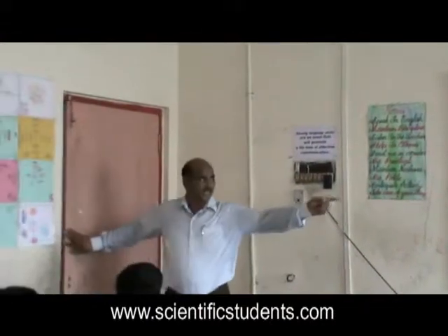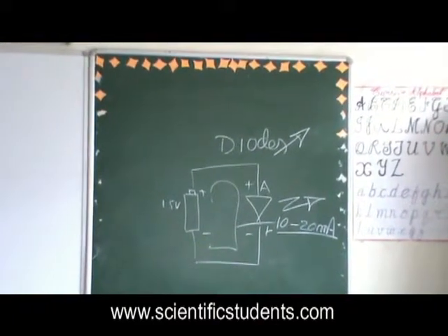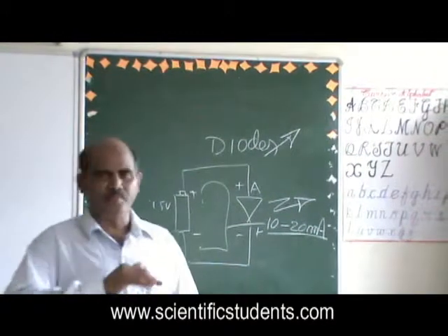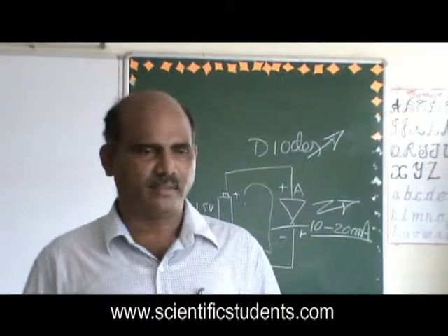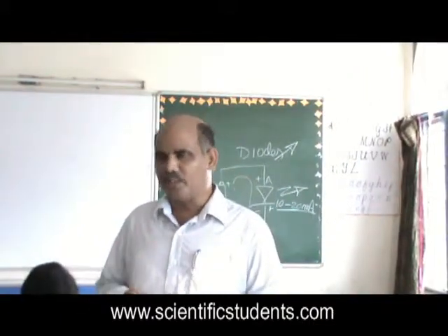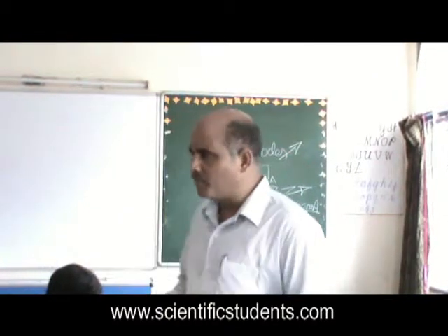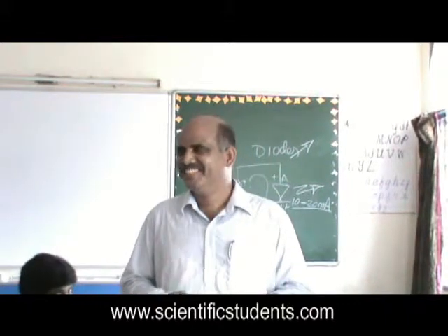Similarly, here in the LED also, they may give you the required light output at 20 milliamperes. So from 10 milliamperes onwards to 20 milliamperes, you are fine with that. Without noticing much difference in the light intensity, you will enjoy that. Okay, my dear friends, but what happened, what did this little boy do?